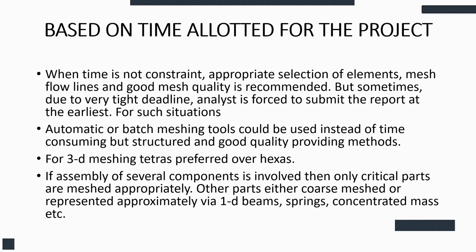Then, based on time allotted for the project. When the type and appropriate selection of the element, mesh flow line, good mesh quality is recommended. Means if time is very less, then you will go for the minimum time or good mesh quality. But sometimes, due to a very tight deadline, the analyst is forced to submit the report at the earliest. For such a situation, automatic or batch meshing tools will be used. For 3D meshing, tetras are preferred over the hexas.